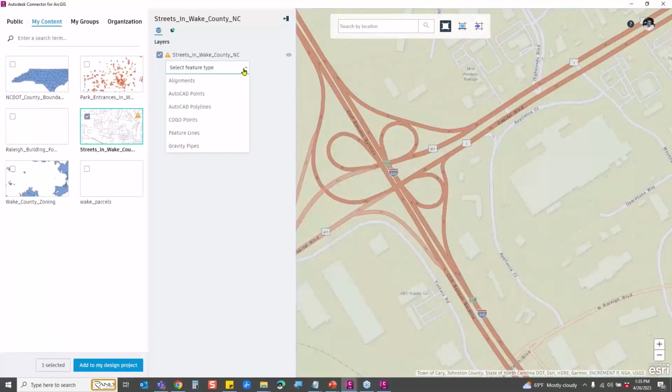And as it runs through it, it does give me the ability of dealing with that line work. See, in earlier releases, it would only create civil elements. I was stuck with bringing in alignments, and all of a sudden, my drawing would become very heavy and all these objects crisscrossing each other. But now I have AutoCAD as an option, and I can just bring in AutoCAD polylines. If it happened to be a feature, a water line, maybe looking at simple things like maybe intersections, or maybe a utility, or maybe just a stop sign, I can bring just AutoCAD objects inside of here.